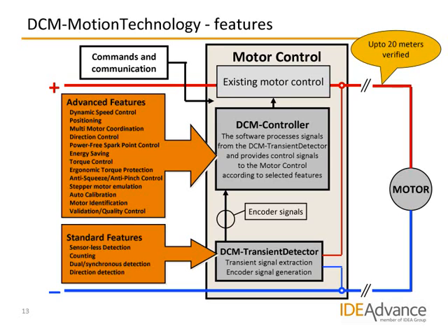Because of the angular accuracy of transient detection, a motor can be stopped or reversed with higher accuracy than most sensor-based systems. This can be useful, for example, for window lift systems with anti-pinch functions in cars. Analyzing the transient fingerprints for complete rotation allows for detection of aging of a motor, since the pattern will change with aging. This is useful for service and maintenance schemes and can also be useful for validation and quality control